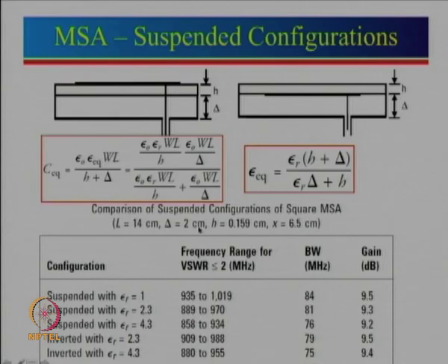So for those kinds of applications, generally one uses a high-cost substrate, but nevertheless cost is always a good thing. So if one can design an antenna with low cost without affecting the performance significantly, and we did notice that the gain just reduces slightly by about 0.1 to 0.2 dB. So in fact, this is a very good way to design an antenna.